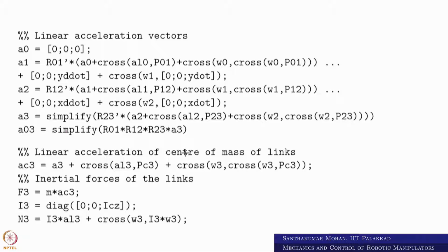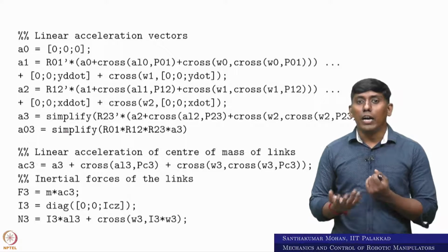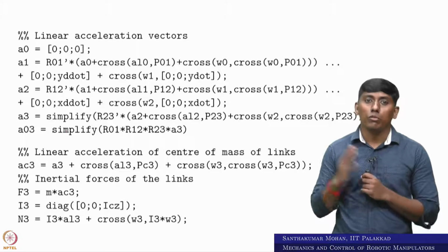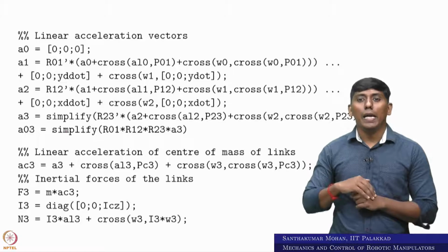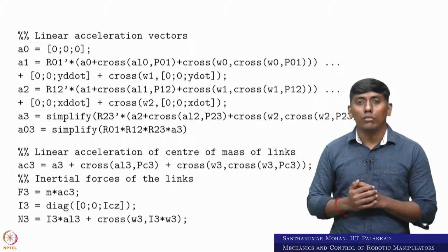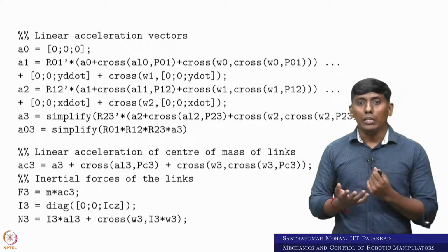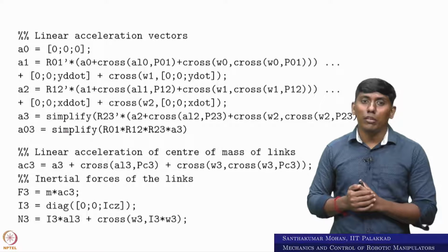The initial effects you need to actually come back to. So here you have initial force and initial moments, right? So what are the initial force and moments? F3 is M3 multiplied by AC3, where M3 is only one body, which is just M, and here we assume that it is in a plane. So in that sense, it has only the centroidal moment of inertia, that too z axis only, the second moment of inertia only. The product of inertia we assume to be 0. So then you can see the initial moment we can calculate.